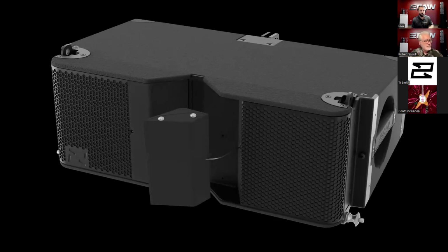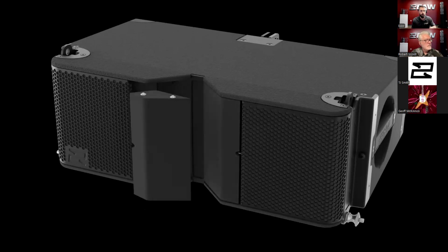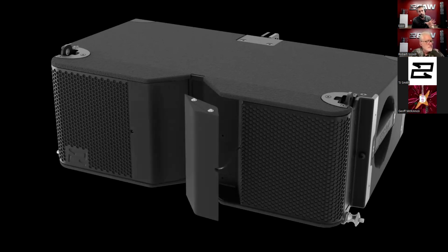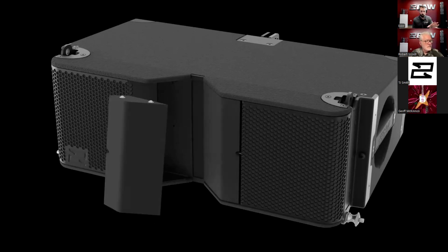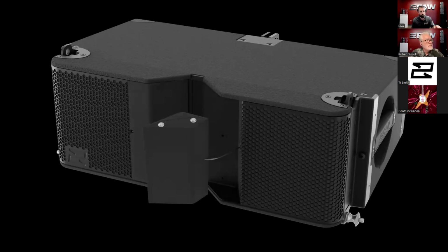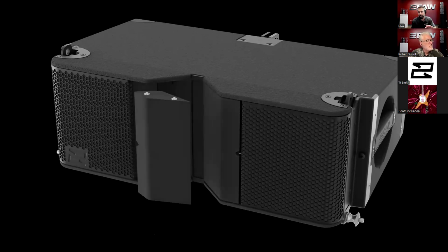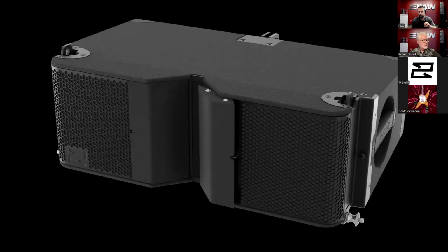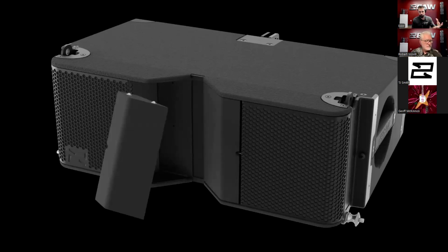You simply push, or at least what I've noticed works best for me is you push on the bottom of the horn part, then you slide it towards the outside of the cabinet, and then you rotate that horn as you see, and then you snap it back into place. A key indicator from watching others do this is that little notch you see where the lanyard is being fed into that retractable lanyard, where it's being fed into the horn flare. That should always be on the outside. So when you snap it back in, if you see that notch on the outside, you know it's in the correct orientation.